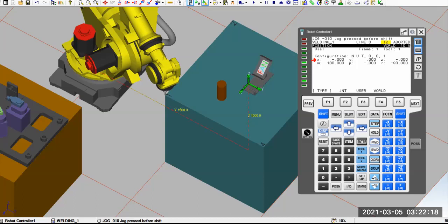X, instead of before being 500, is now 0. Why? Because right now your robot is at the user frame 0,0,0, right? So that's why you have 0,0,0 here. You understand what we get as the result now, right? If you look from world, world tells you, if we go back to world, 500, 1000, 330, that's from world, right? That's from the default 0,0,0, somewhere around here. That's the 0,0,0 on world.